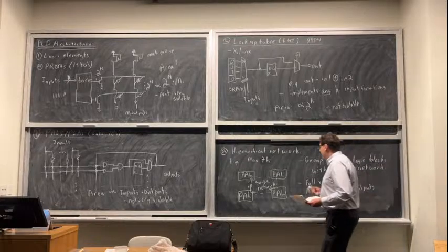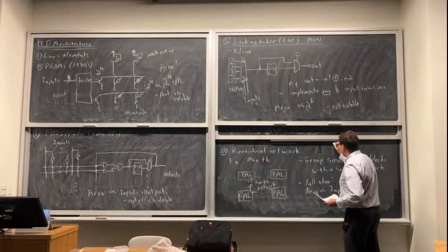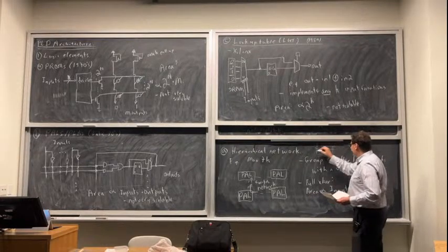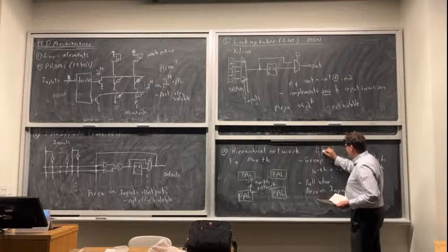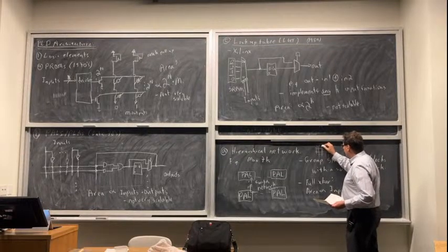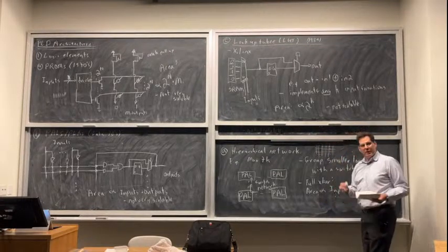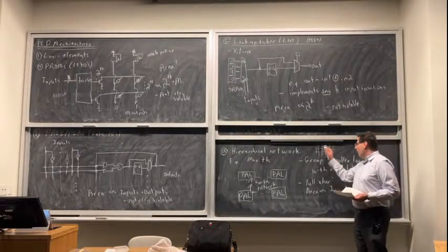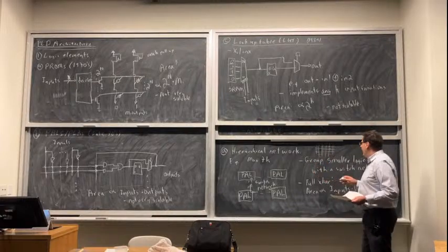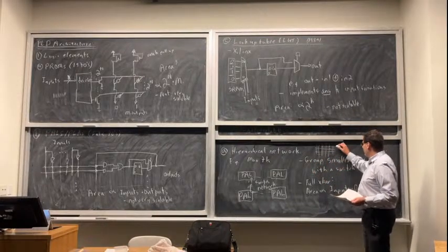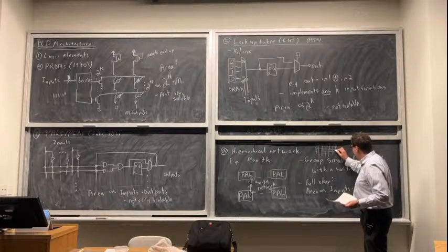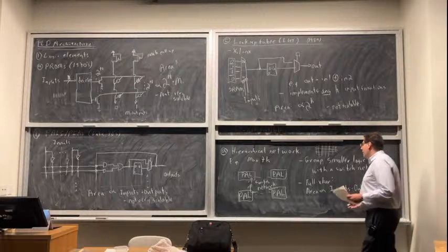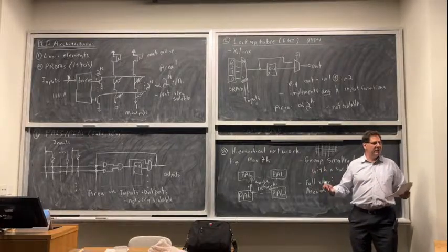So, I mean, it's not too hard to see why. One of the ways that these can be built is you basically make a wire for every output, and you make a wire in the other direction for every input, and you put some kind of programmable switch wherever they cross. And you can pretty quickly see the number of programmable switches is like n squared. You can also build them with multiplexers instead. If you build them with multiplexers, you wind up with one multiplexer for every output, and the number of inputs is equal to the number of inputs to the whole crossbar. That actually also grows as inputs times outputs. So either way, you get this behavior.